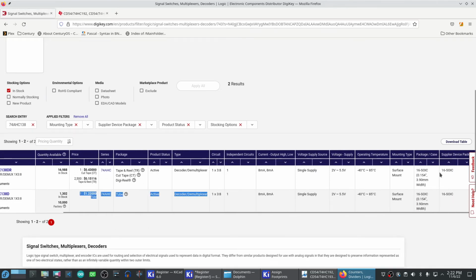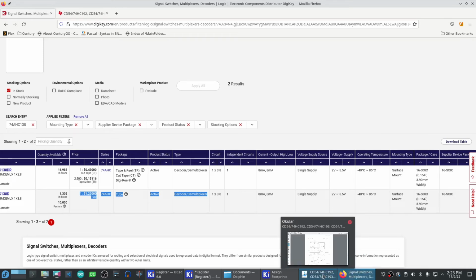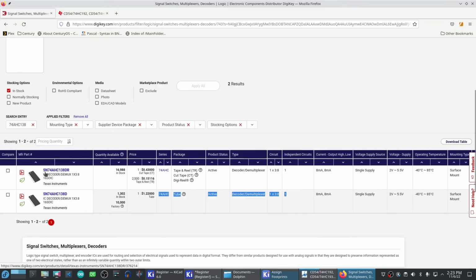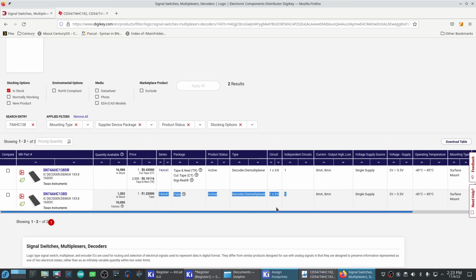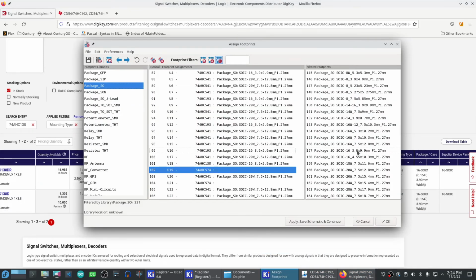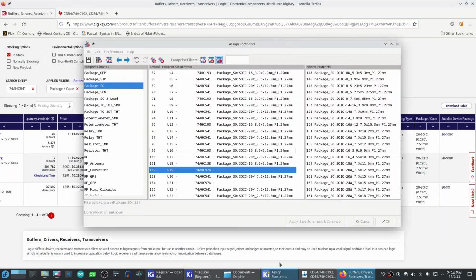These are 3.9 millimeter width, 16 pin. So these are the same footprints here. All right, let's double check and make sure I didn't do something stupid with the 541s, width of 7.5 millimeters. So that is 7.5 millimeters. So that's good.